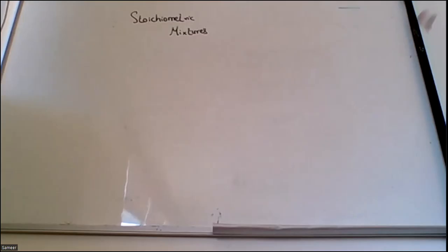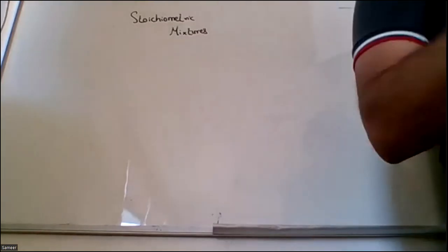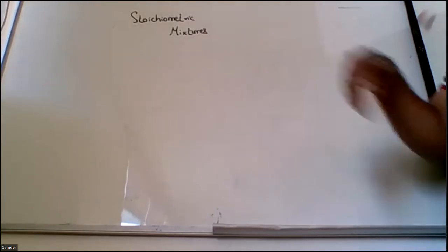Combining the first lecture and today's discussion, we have discussed that water and carbon dioxide have always been among the most effective agents. But water and carbon dioxide cannot be applied on all types of fires, right? For example, if I have any type of metal oxides, water and carbon dioxide are ineffective. Oxidizers, your nitrates, nitrites, chlorides, persulfates, chlorates, bromates: water is ineffective on all of these, and similarly carbon dioxide is also ineffective. Why? Because they are oxidizers. But stoichiometric mixtures are different from there.